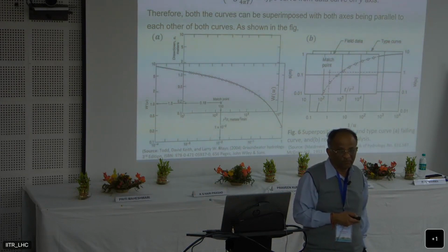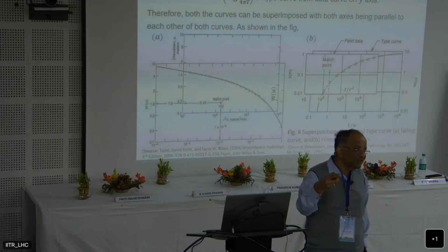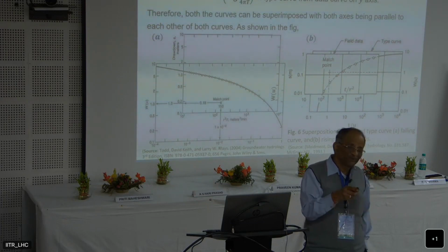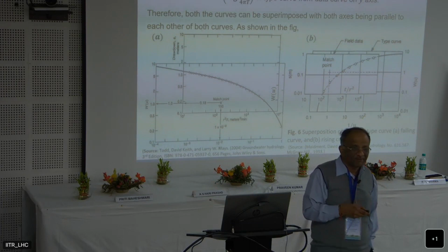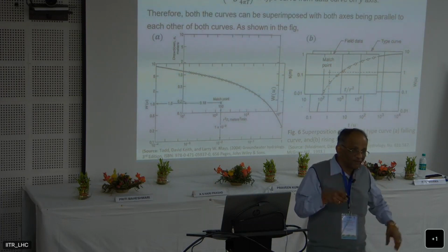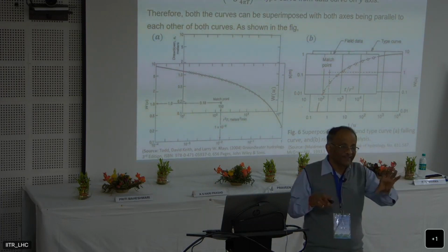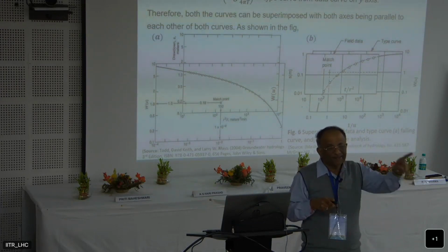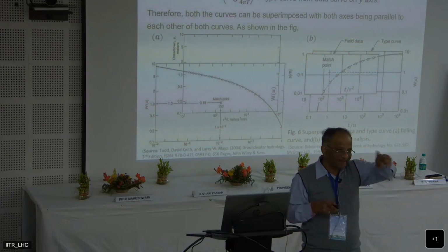For our purpose, we calculate U as S r square over 4 capital T small t. We could have called it W of X for all that it mattered. Basically, W is a function of U, and this W is called the well function, but there is no name given to U. This U is a function of r square S by 4Tt, which really represents the aquifer information.